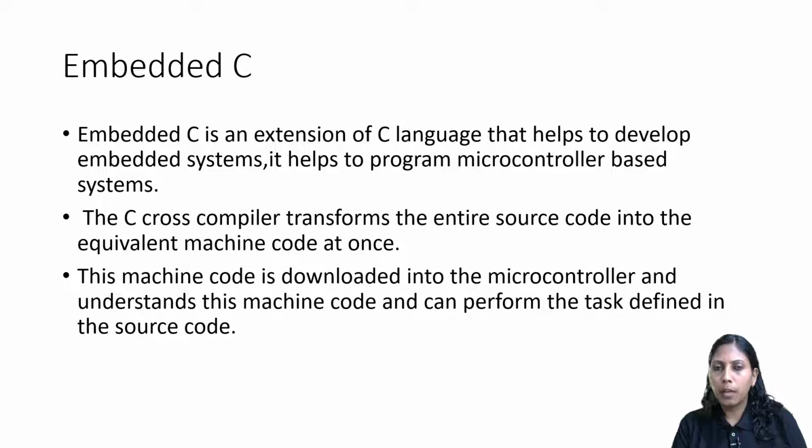For example, if we are using an x86 processor as the host machine processor, and I did an LED blinking project or a home automation project there, and I would like to transfer that to the target machine, which will be a controller, any 8-bit, 16-bit or 32-bit microcontroller, then how can I run the same program which I tested on the host machine? How can I transfer this code to the target machine? That is possible with the help of cross compilers.